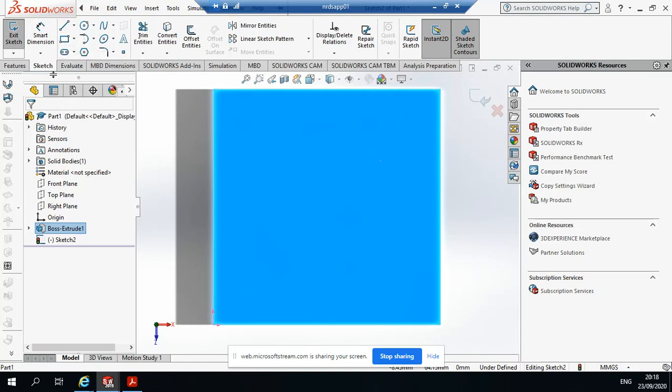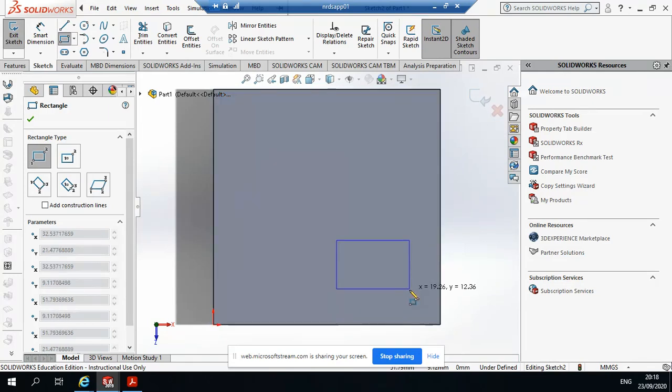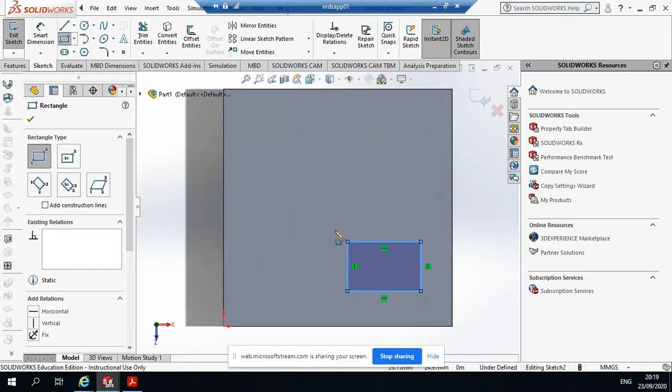So if you go back to Sketch and Rectangle, select it. You can draw a rectangle anywhere around here. Again, be careful and leave a bit of a gap here for us to define that it's 10 millimeters out. If we drew it too close and we say 20, we might get a rectangle sticking out over here somewhere. And it just means we can still do it properly. It just means we have a little bit more maths and a little bit more hooking about.